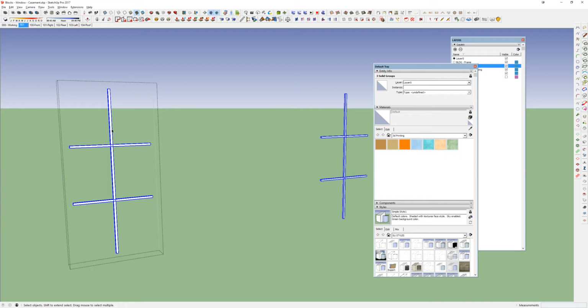I like having containers on a layer, because otherwise I can really get into an issue where if I explode something, then geometry gets put onto a layer I don't want it to, and it just starts to create a big mess. So I try to never put very specific things onto layers. I'll make containers that are on the layers. So I'm hoping that makes sense.